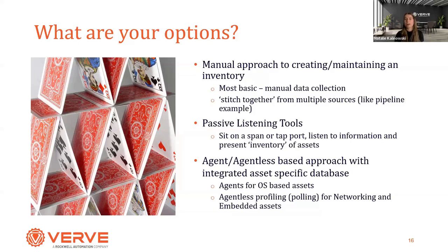Inherently, when you have vulnerabilities, the CVE and CVSS scores are always mapped to the actual vulnerability within a device, not to packets of information going back and forth between devices, because that's not helpful. And then another aspect of it is being able to see embedded devices, because if you're just passively looking for information, you don't really dive deeper into that OT environment where we have embedded devices, where you have to go through a backplane of a rack to find slots and cards.